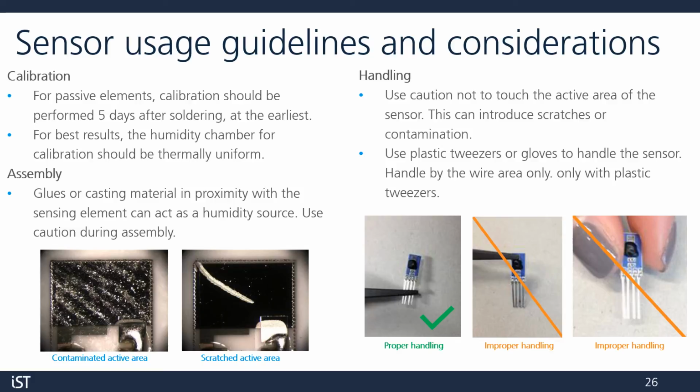Our recommendation is to always use plastic tweezers, gripping the sensor by the wires, as shown here. If you don't have tweezers and you use your hands, be sure to wear gloves and avoid touching the sensing area.